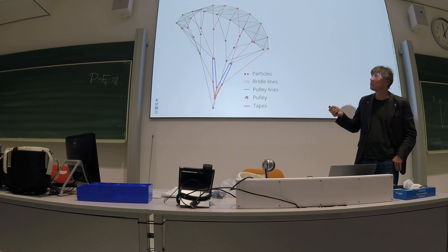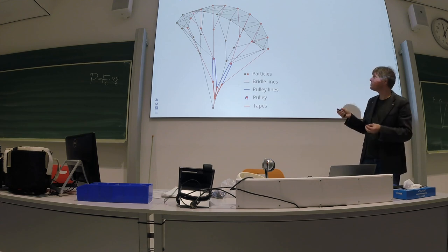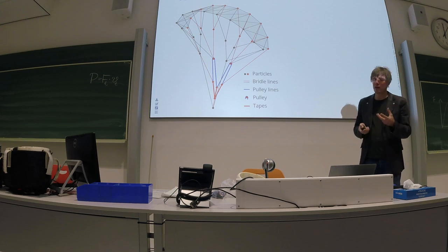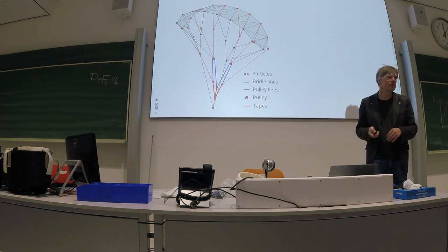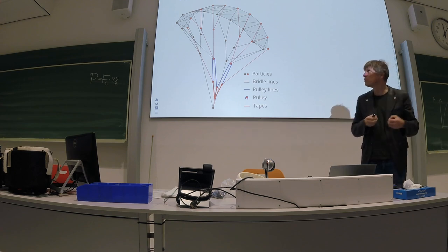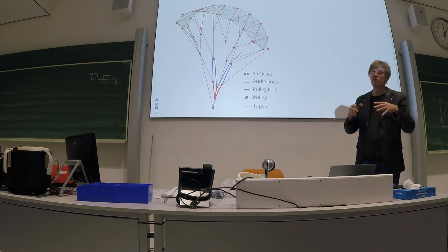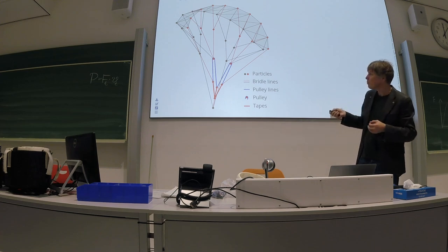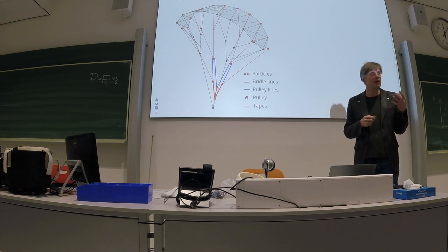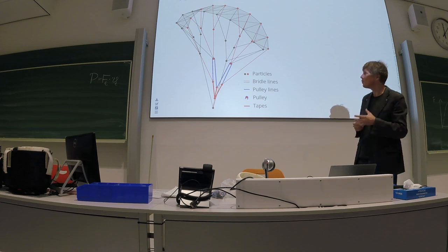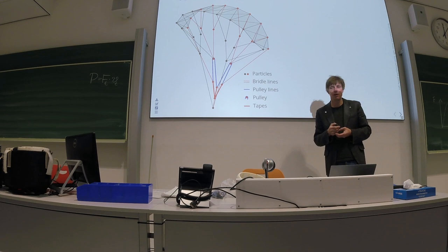Each dot here is a mass particle that represents its part of the wing, and these particles are connected with springs, elastic springs and dampers, and we were able to simulate the deformation of this wing as a result of the actuation to quite a high degree of accuracy with such a particle system, all in real-time capability.